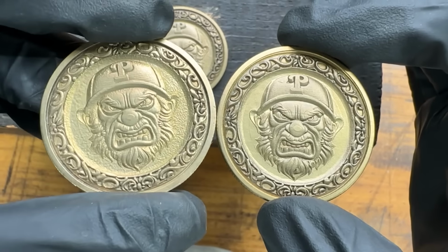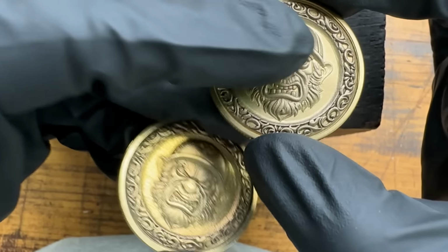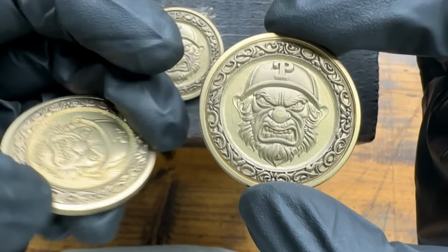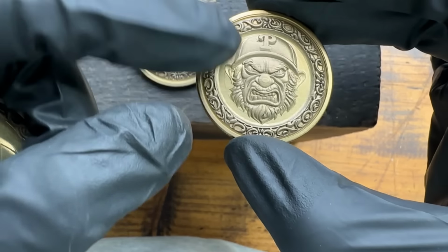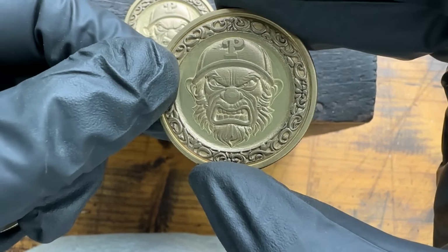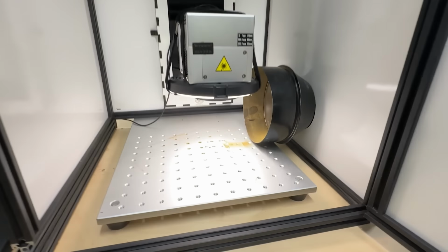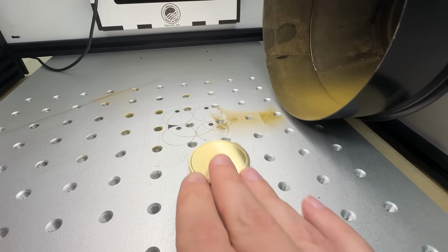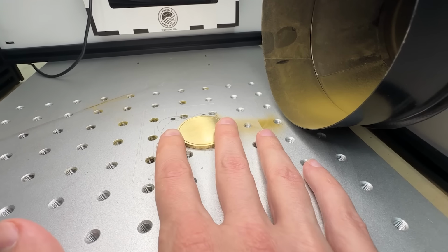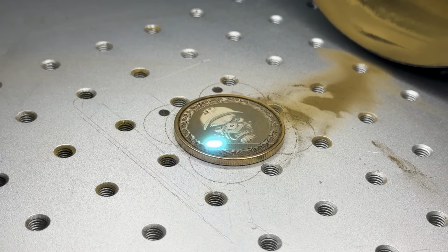But yeah, this is a really, really interesting comparison. And it's definitely got me thinking. I might start running at a slightly higher frequency than I normally do if I can still get results that look like this out of the box. And that's just what I did. My curiosity got the best of me, so I grabbed another blank coin and I went back in LightBurn. I changed two things. I bumped the power from 80% up to 90%, which is closer to the range that I normally use. And then I changed the frequency to 100. Let's see what happens.